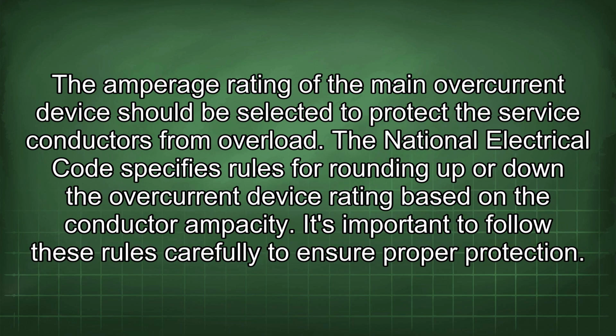The amperage rating of the main overcurrent device should be selected to protect the service conductors from overload. The National Electrical Code specifies rules for rounding up or down the overcurrent device rating based on the conductor ampacity. It's important to follow these rules carefully to ensure proper protection.